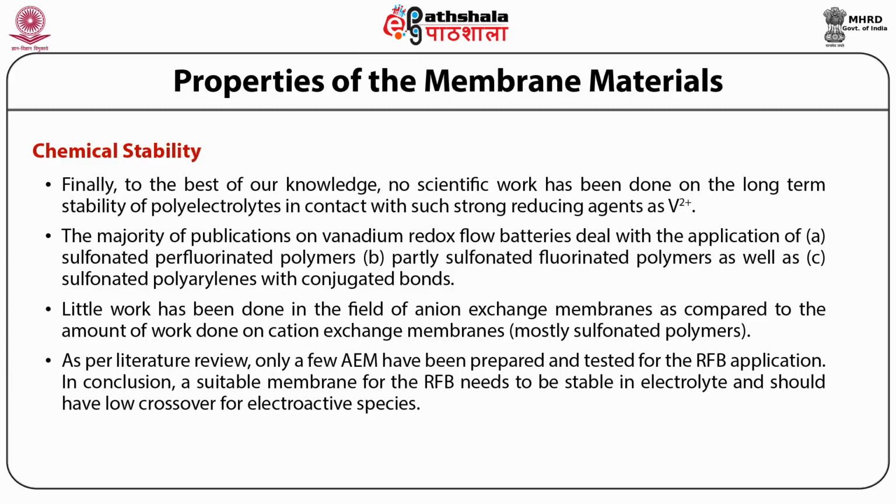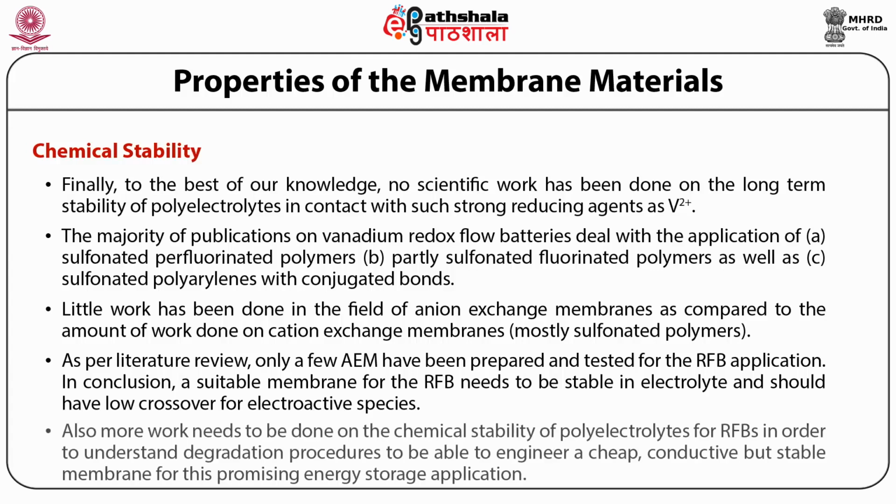In conclusion, a suitable material for the RFB needs to be stable in the electrolyte and should have low crossover for electroactive species. Also, more work needs to be done on the chemical stability of polyelectrolytes for RFBs in order to understand the degradation procedures, to be able to engineer a cheap, conductive but stable membrane for this promising energy storage application.